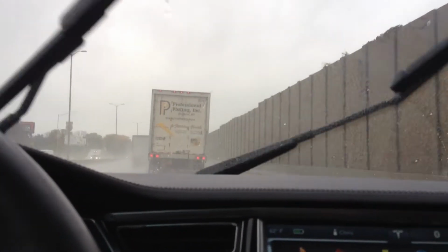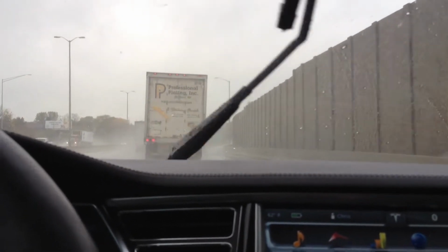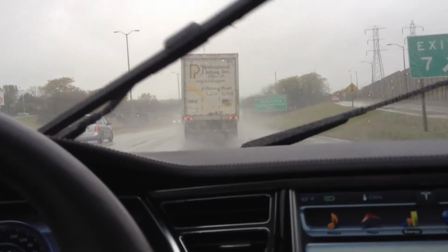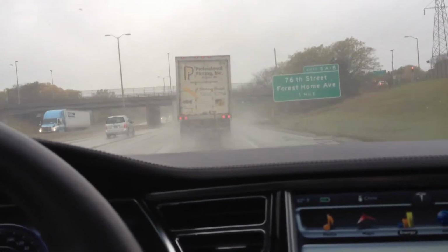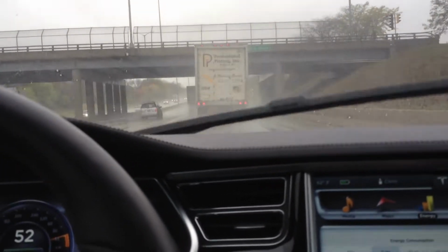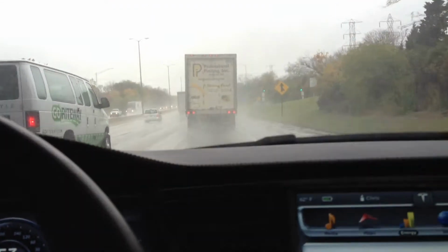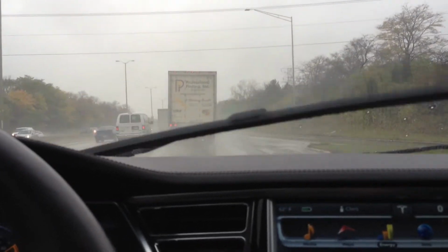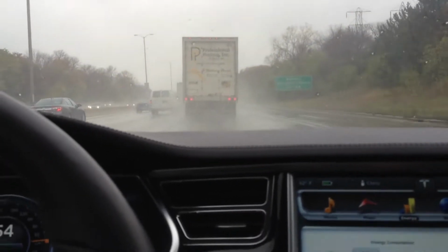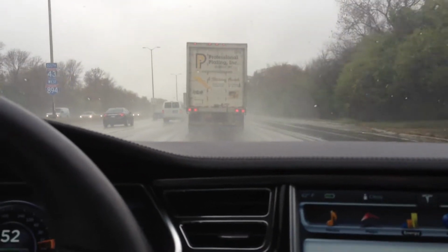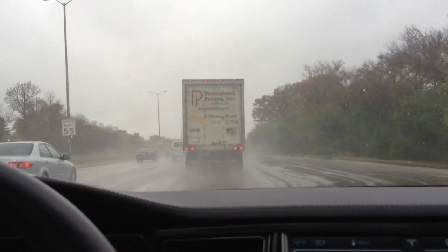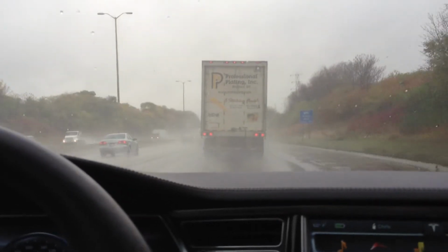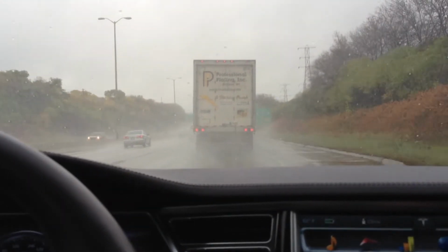But anyways, I believe I was talking about the consumption, how to calculate how much a charge is going to cost you, and how much the different voltages during charging can affect your charging time. I'm not going through all that again for a third time. So, long story short, the Tesla Model S single charger using a NEMA 14-50 adapter at 250 volts, 40 amps, its maximum, will draw 10 kilowatts.